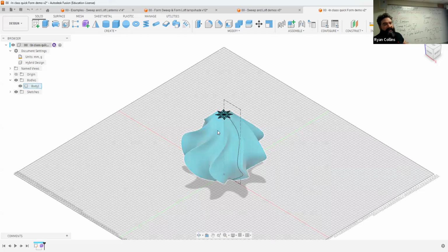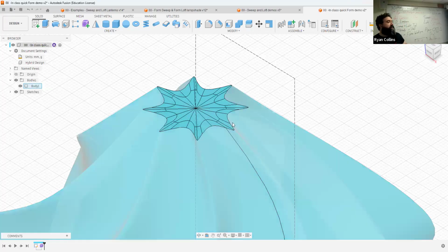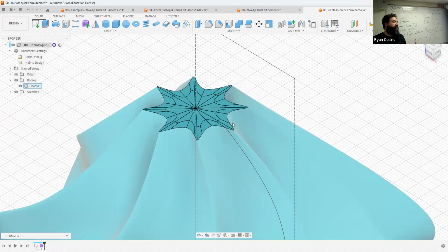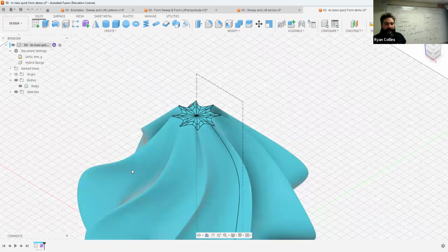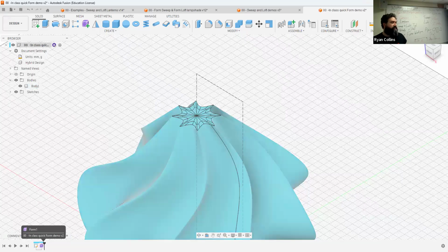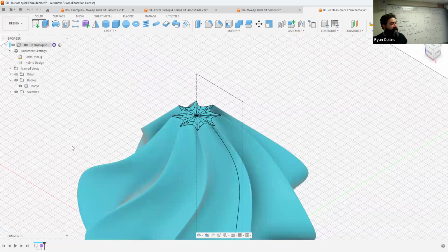So play around with it. If you run into trouble, if it gives you errors, first, always save before you go to finish form. Always save. And then if it gives you that bad allocation error, it's because of this transition. Step back, do them one at a time. If one works and the other doesn't, fiddle around with the other. There you go. Hopefully it fixes for you. But again, as you can see, there's no additional history being captured by the history bar. And that's just one of the issues you have with form space.